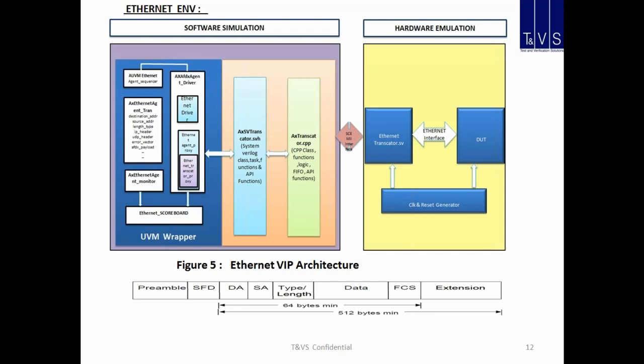For that, we need a different transactor, because this transactor cannot be generalized. It is interface specific. So if you move to a different interface, you need to build a different transactor. A lot of people use emulation for SoC verification. And as Surinder mentioned, you often do it for performance as well. So you put the whole chip on there, you put the software on top of the chip. This then allows you to drive traffic in from X.